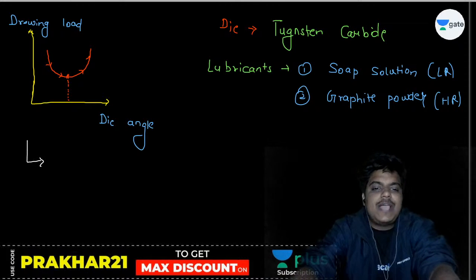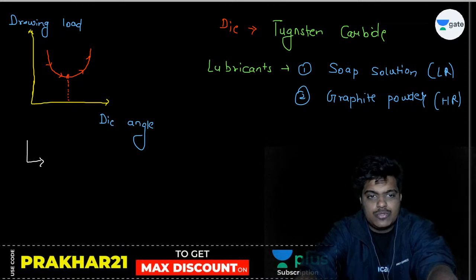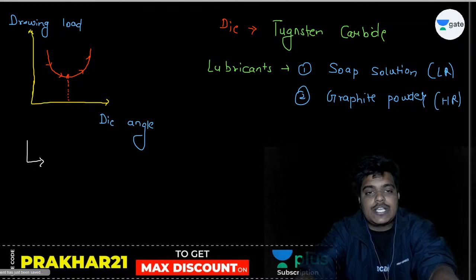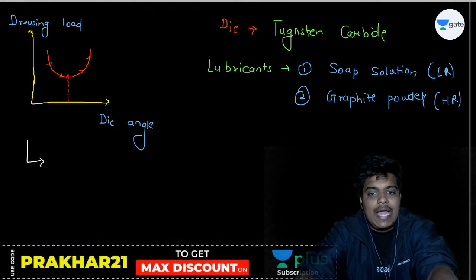ठीक है, lubricants भी आपको समझ में आ गए कि कौन कौन से lubricants यूज होते हैं. The approach section, die land, everything is written. That approach section लिख लो. Approach section is used for the reduction in the size. Die land is provided for the stability of the reduced part, and relief section is provided for the elastic recovery of the material.